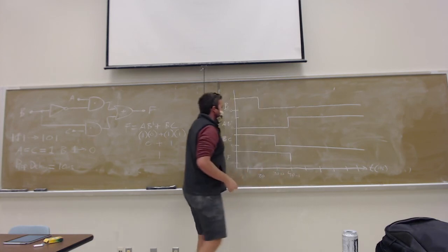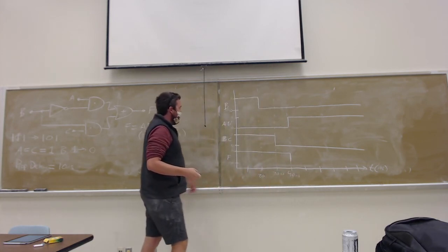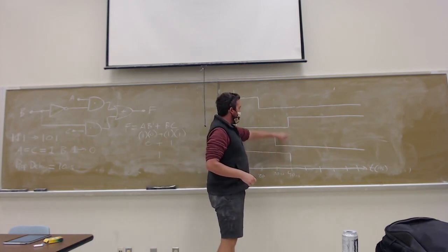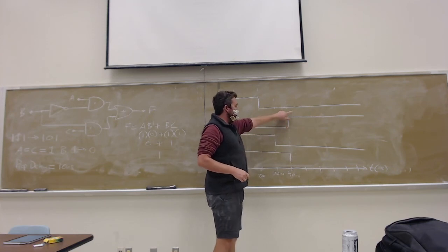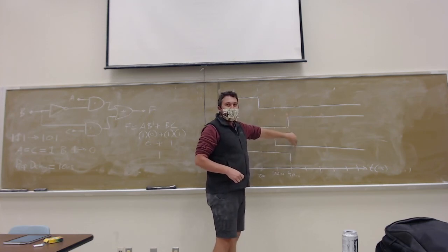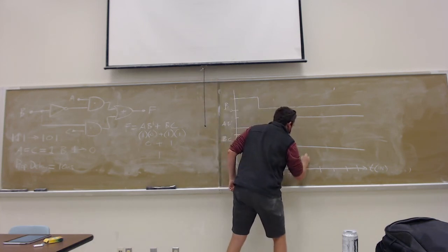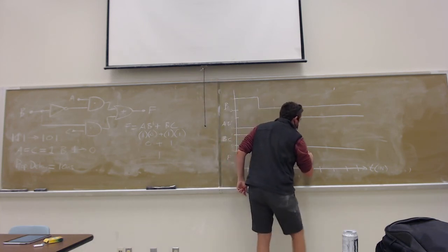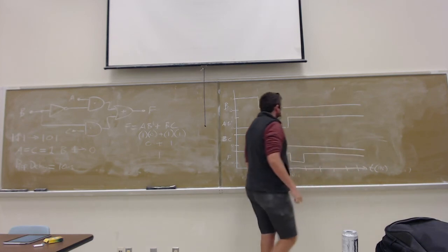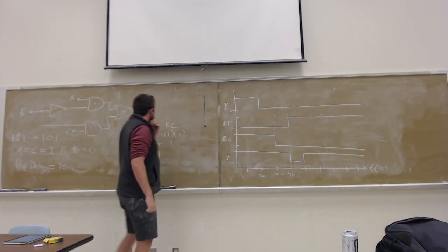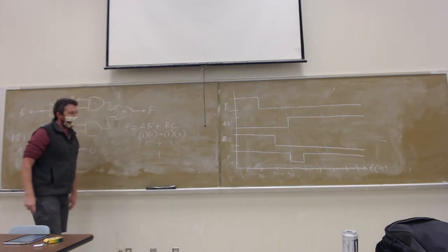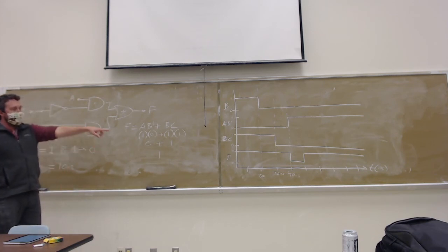So it's going to go to 0. But at the same time it went to 0, A, B prime went to 1, so then we had 1 or 0 again. Which means 10 nanoseconds later it's going to go back to 1. And then it's going to stay there forever. So each 10 nanoseconds it switches from 0 to 1. Well, just in this case, that's what I'm saying.